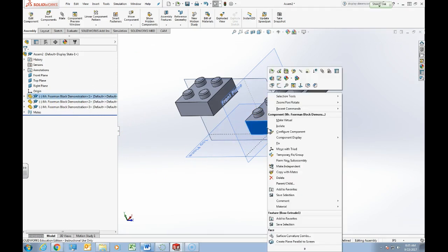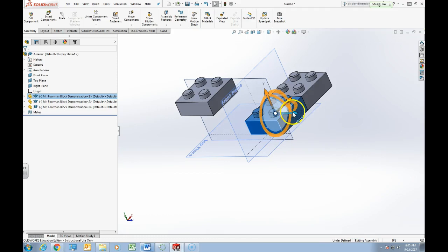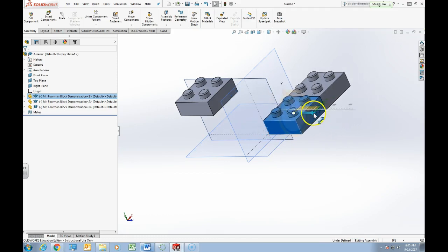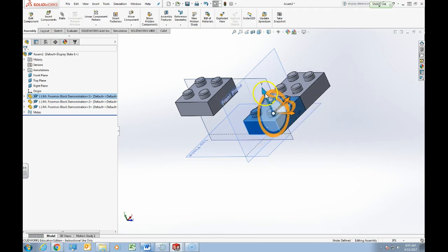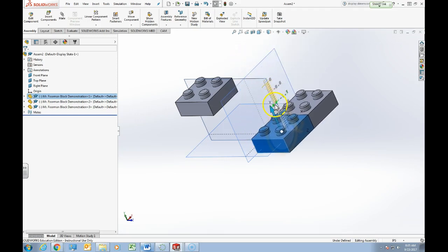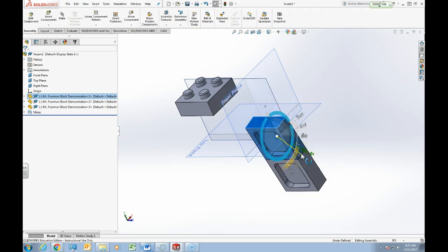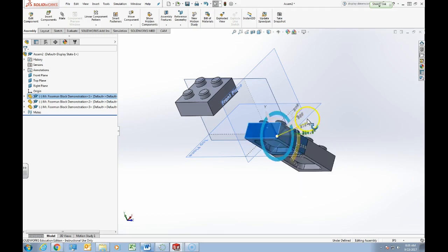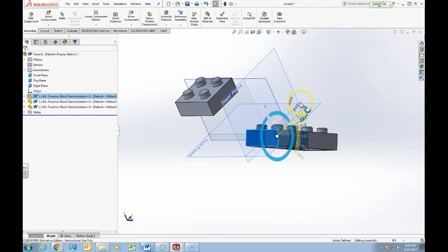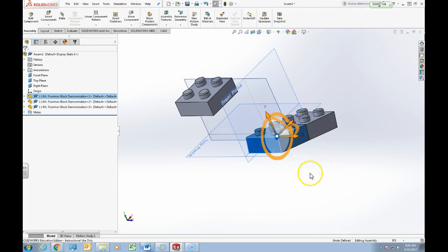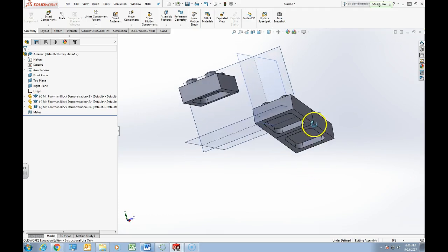If you right click on that part itself, there's this option, move with triad, when you're here. This is a very helpful method. Now that that part is floated, you can move it more accurately in any orientation. But now that it's fully floating, I can actually rotate it and do all sorts of other funky stuff. So tell you what we're going to do to start. See how that could be kind of off cattywampus in space that way.